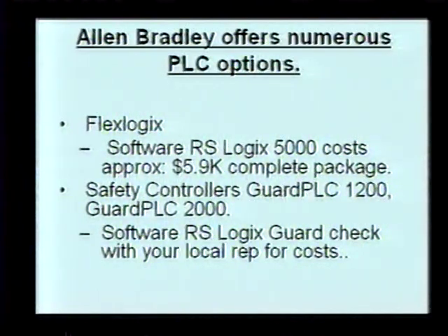One of the biggest safety issues is the local emergency stop. You see that large red push button on a control panel. That large red push button should never be wired solely to the PLC. It needs to be hardwired outside of the PLC, so when somebody hits it, it knocks all the output power off the output of the PLC, or even shunt trips a breaker if you would like. Some people like to knock all the outputs out physically off the switch itself, and then in addition send a separate signal to the input of the PLC to tell the operator what has happened, that the local emergency stop has been pressed.